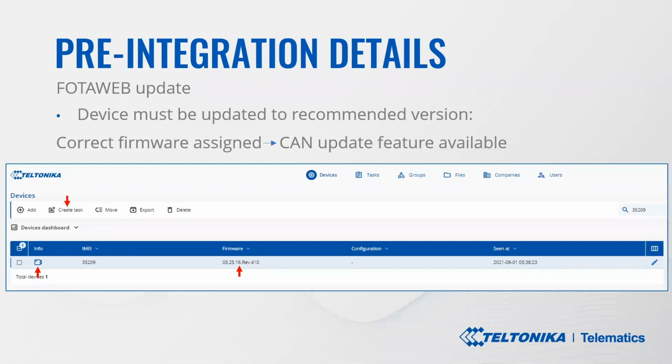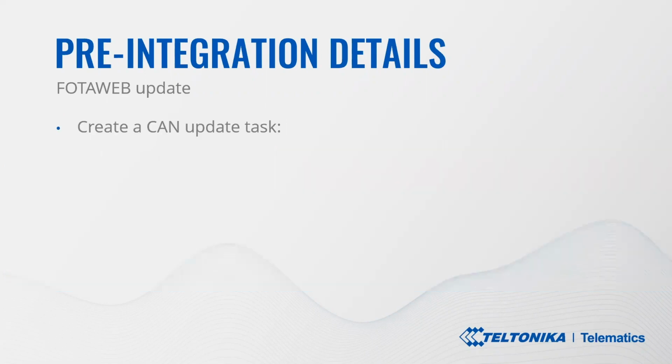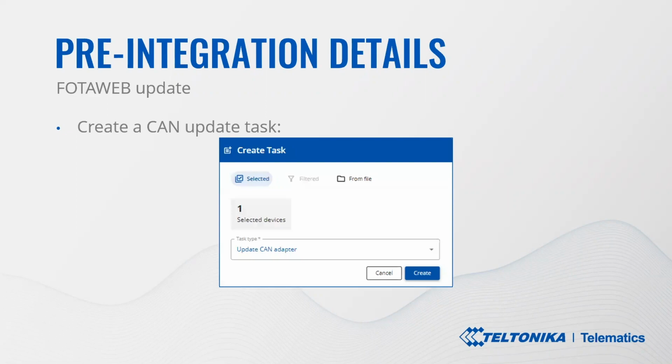When the number of units is selected, the next step is to create the task. The create task tool allows you to choose a number of options for the unit. However, to proceed with the CAN update task, you have to, of course, choose the update CAN adapter task type. Afterwards, when you choose this type, the task is placed into the platform and the platform awaits the unit to connect.